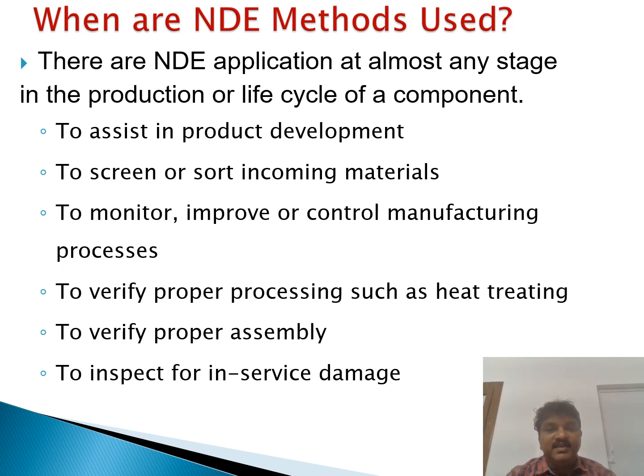There are NDE applications at almost any stage of the life cycle of the component: to assist in product development, to screen or sort incoming material, that means raw materials, to monitor, improve or control manufacturing processes, to verify proper processing such as heat treating, to verify proper assembly, to inspect for in-service damage.